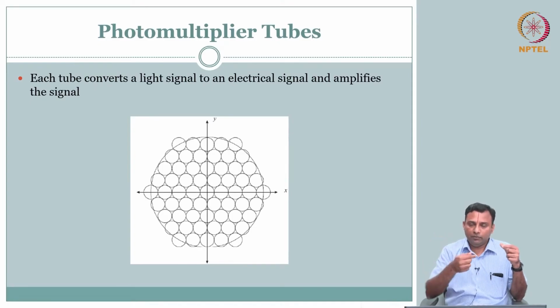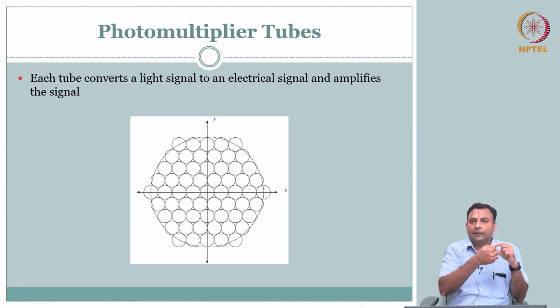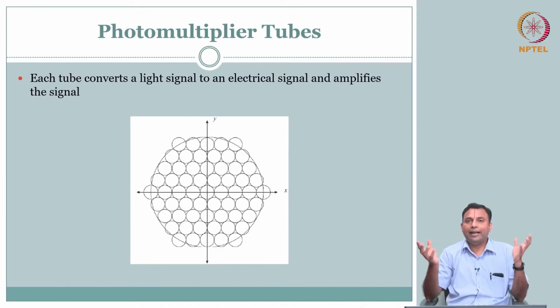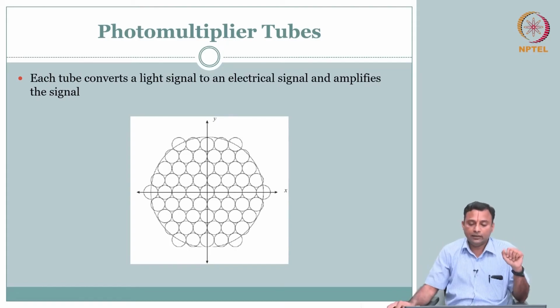So the gamma rays come, first they are collimated, and after that the gamma photon hits the scintillation crystal. Out of the scintillation crystal you get light photons, some number depending on the conversion. But then here we need to have two things worked out. One is, I need to be able to amplify the signal, and the other thing is